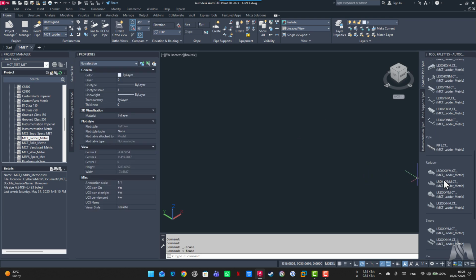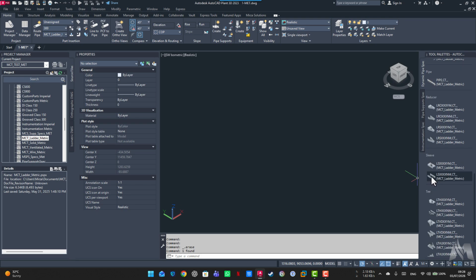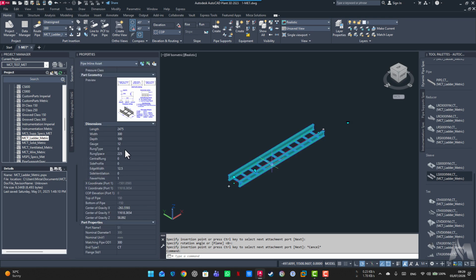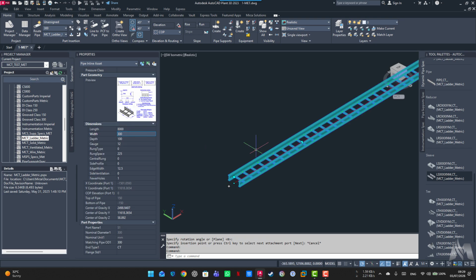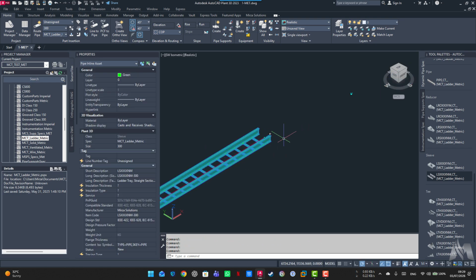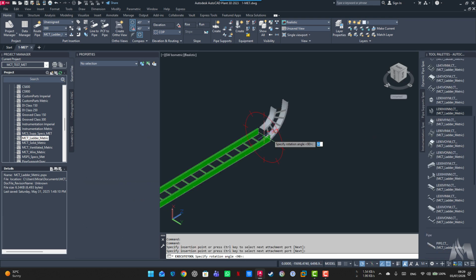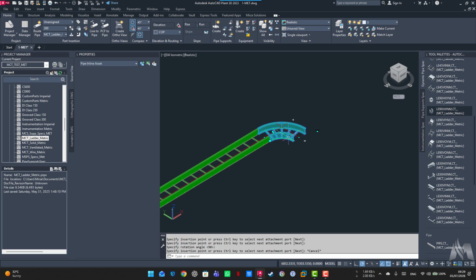And if I want to make a cable tray system, I will start with a straight section, which is a sleeve over here, and just simply I will place it. And let's say I want it to be 8,000 mm. Okay, I will change the value to 8,000. After that, I'm going to place an elbow, horizontal elbow, and this is placed over here.